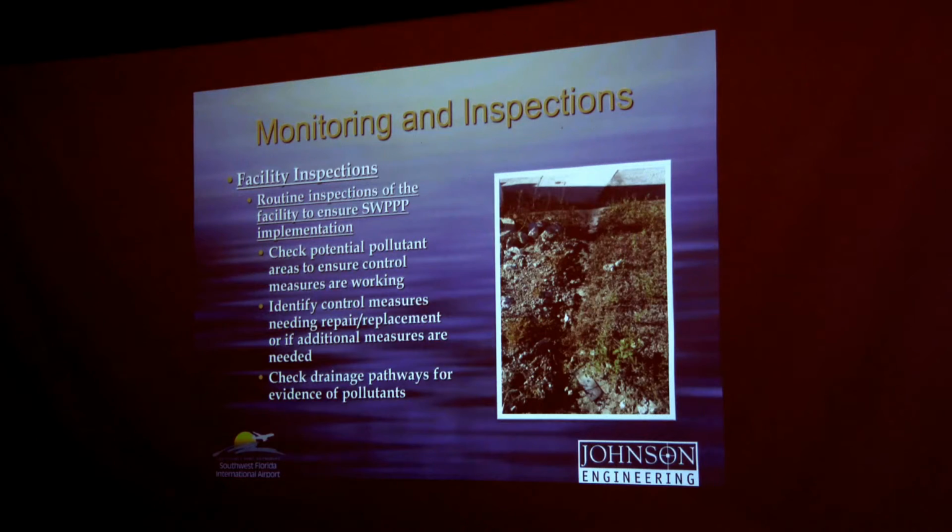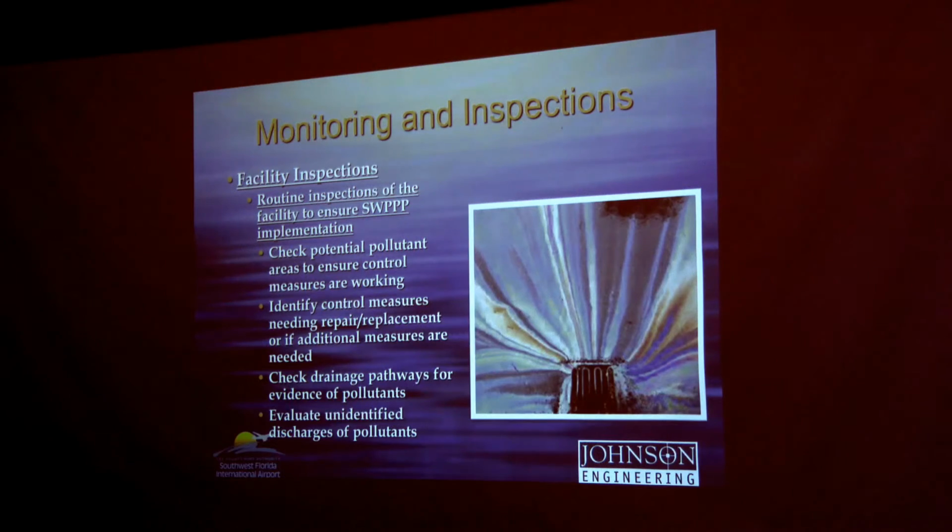And then check drainage pathways for evidence of pollutants. This is a little rill that was established by the trash compactor facility. This is just a small erosion area caused by stormwater that could potentially get pollutants into the stormwater management system.